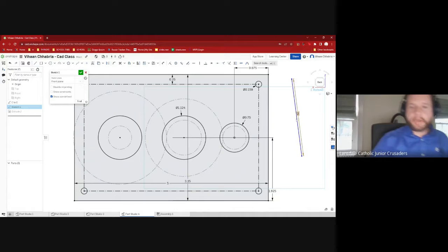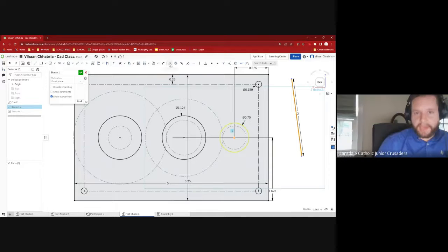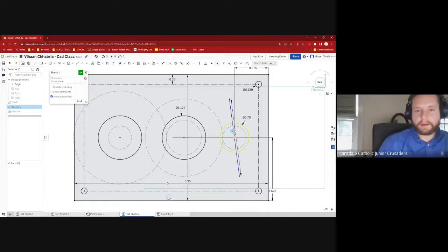And then I want you to click the line. Yep. And then click the center point of the circle that you're trying to go to. And we're going to use a new midpoint. Yes, exactly. You see where I'm going. It's over to the right. That's coincident. Midpoint's way over to the right. There you go.